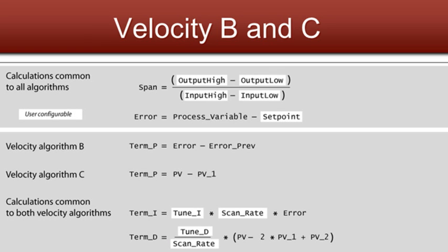With the type C, set point changes are essentially going to be invisible. You, the user, could type in a set point change, and the PID calculation is only going to pick that up as the process variable, through the error and through the I term, not through the gain.